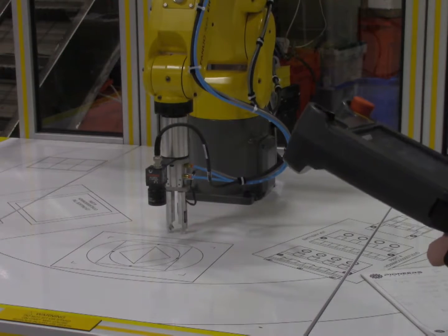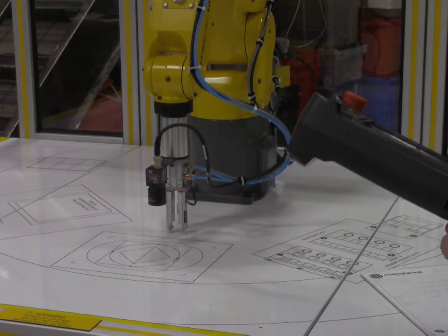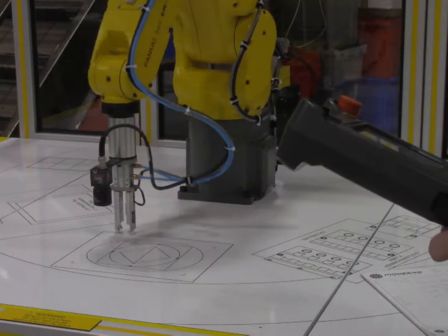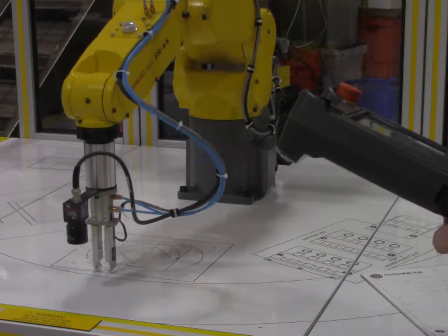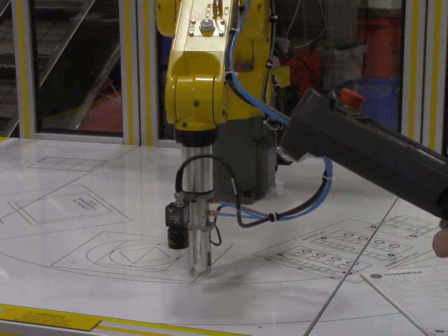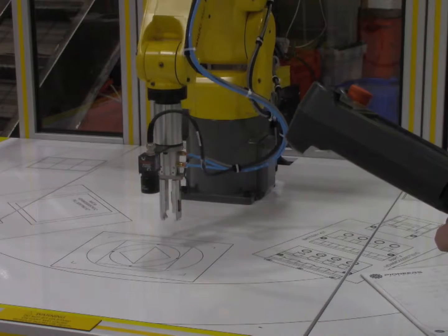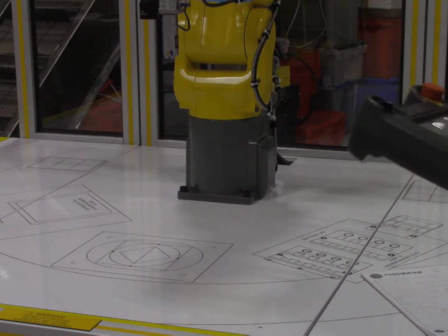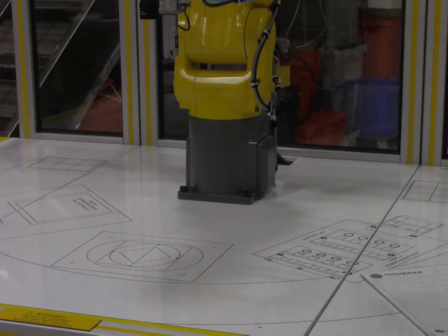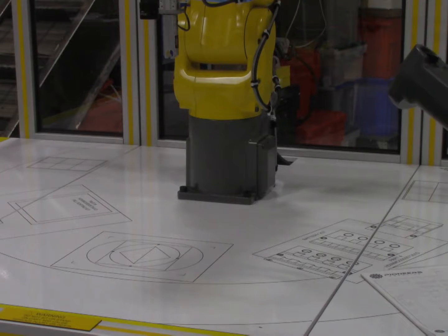Oh, it looks like I may have on and off reversed on these. It could just be a couple of pneumatic hoses, but I'm just going to keep going. Just stepping through the program one line at a time, and we should see then the gripper do the opposite behavior once we get down to the end of the program. So it should go to position register number 1, and then the next thing it should do is, there it goes, it snaps that gripper, and that didn't show up real well on the video, but I did hear a psh, psh. So it is functioning. And if we go back to the beginning, there's our alarm again.